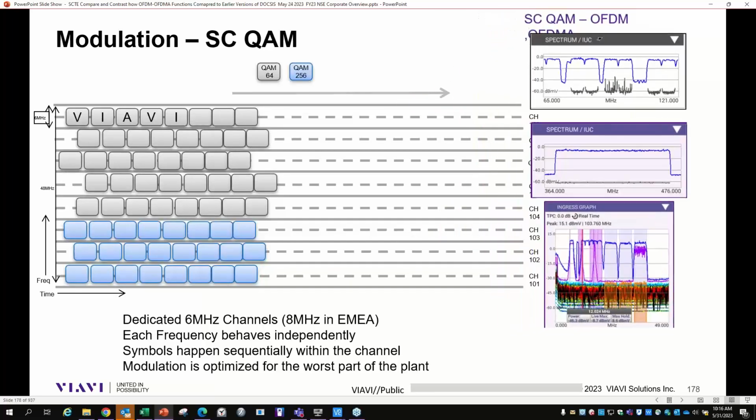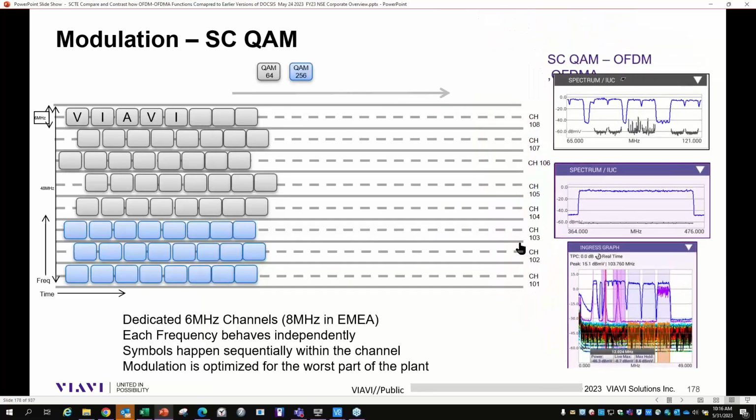All right. So again, when we look at single QAM carriers themselves, think about the ability to handle FM ingress, versus an OFDM carrier with very little ingress, right? Optimize the network in order to have maximum profile capability, and then the OFDMA carrier on the upstream, which we'll talk about later on, and how to segregate that from single QAM carriers as well. So just three different views: upstream and downstream capability.